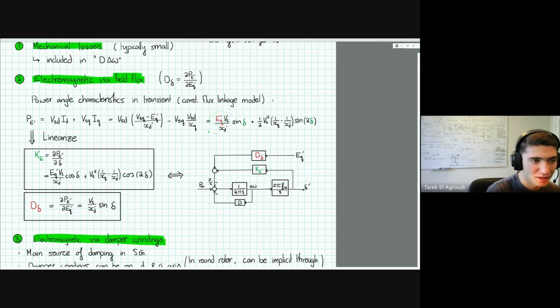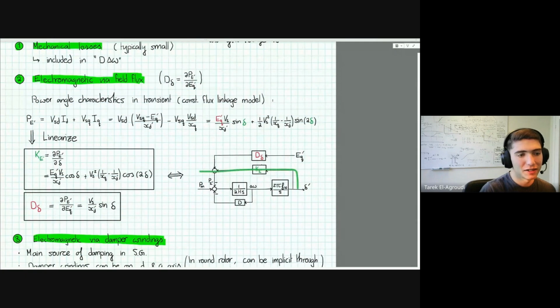So in the transient case, you of course use the transient values. If you derive that with respect to this EQ, then you get some linearization constant there as well. And again, you have the same for the electrical power synchronizing constant, where you have just taken the derivative with respect to the power angle. So you can linearize this electrical power with respect to these two variables.